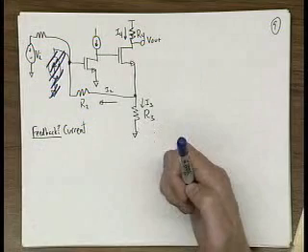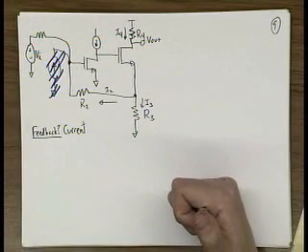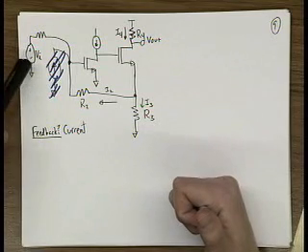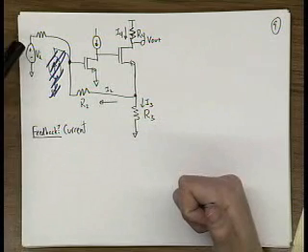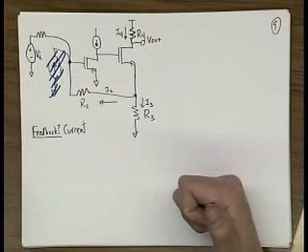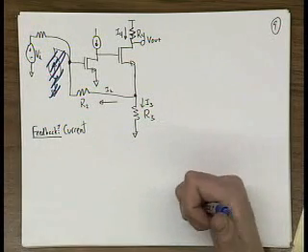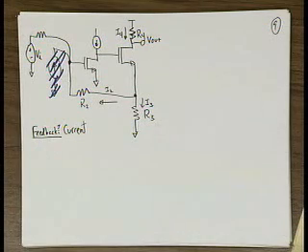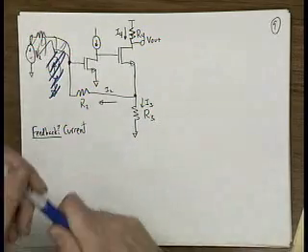What are we feeding back now? A voltage or a current? We're still feeding back a current, even though the input source is a voltage, like this is a Norton equivalent, Thevenin equivalent to a voltage, to a current source with just a shunting resistor, right? And so what you have to realize is that sometimes the input and output terminals, or the input and output stimuli, are not a direct indication of what you're feeding back.